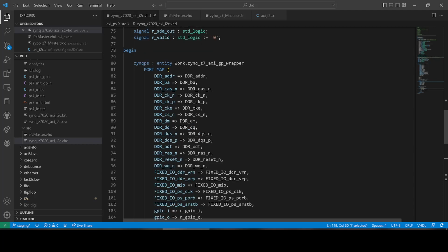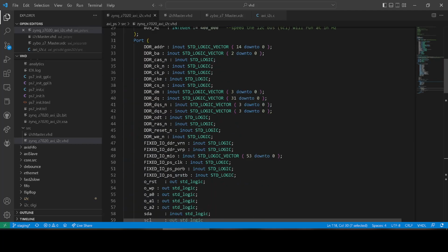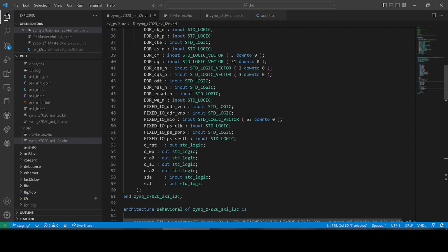And so I've instantiated it, and I basically told it to create an output like it would have had it been the normal wrapper, but with the signals that I needed, which were setting the address of the EEPROM itself, and setting out, because I have an LED for whether it's reset or not reset. And then here is my I2C bus, where SDA is an in-out port, which always has to be on your top module. So I linked the block design to my master so they'd communicate.